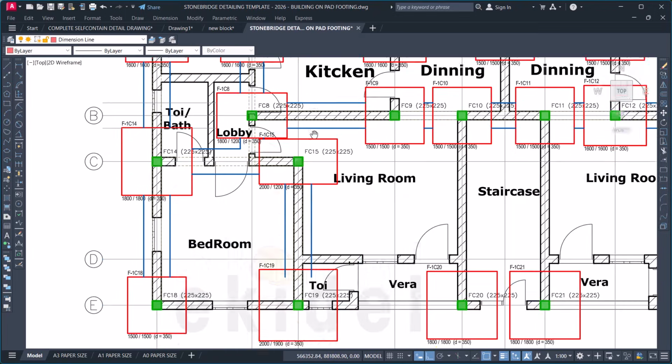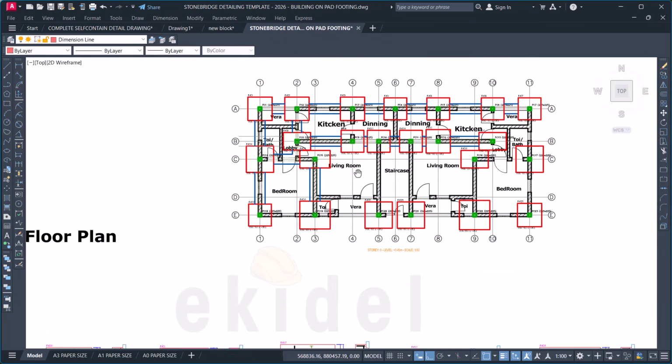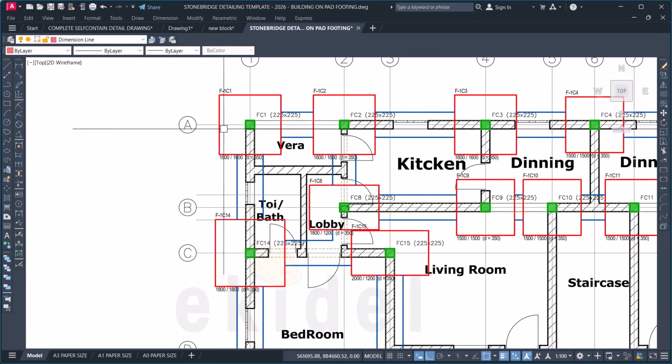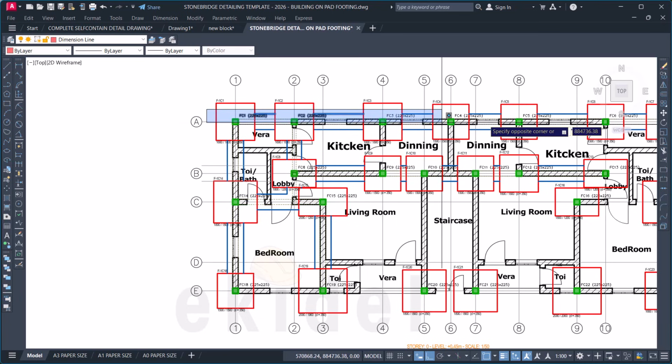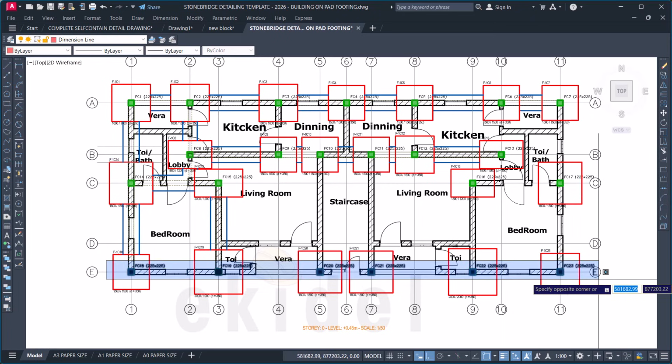That's fine. And again, I will come now, click on this line now, TR, enter, and then trim off this and trim off this. So we now have also a digging here. Now just to be fast too, since I already have a footing trench around this line on this grid line A all the way down, we'll have a digging also on this grid line E all the way down from here to here. You can see the block wall there.